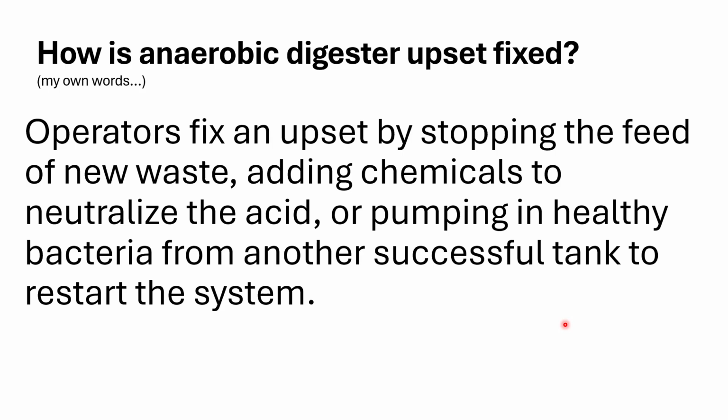But you stop feeding new waste into the digester. You can add chemicals. Remember that lime and that calcium carbonate. What that's going to do is neutralize the acid, just like a Tums will. Okay, and you can pump in healthy bacteria from another tank, another digester, to restart the system. That's called seeding your digester. Okay,